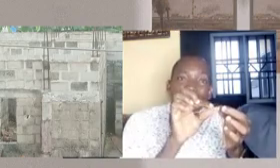It's likely to still be 2, because the other one coming from the other end is 2 bars, so it's going to take 2 to this end and 2 to the other end. So what's going to happen there? In that particular area, every load is going to send serious tension at the end of that pillar, thereby causing cracks on that building with time. Sometimes you don't get the effect immediately, but with time it is bound to happen.